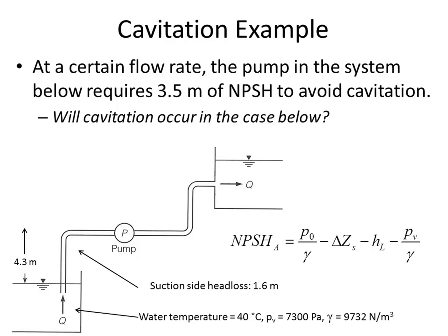And then the other thing that favors cavitation is warm water, because the warmer the water is, the higher the vapor pressure will be. And so that will also be another thing that's subtracting from the available head. We want there to be a big available head, and so we want to minimize these three things that can reduce the suction head that's available. And then the other part of the equation, of course, is picking a pump that has a low requirement.